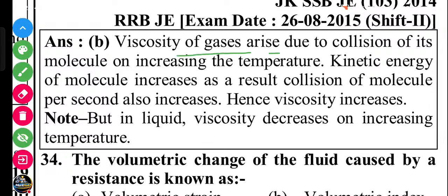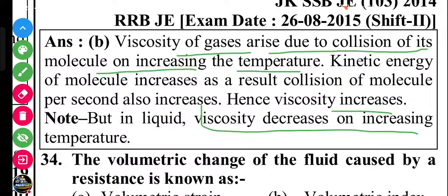Viscosity of the gases arises due to the collision of its molecules. On increasing the temperature, the kinetic energy of molecules increases as a result. The collision of the molecules per second also increases. Hence, the viscosity increases. But in the liquid, viscosity decreases on increasing the temperature. You comment: what is the cause of the viscosity in liquid?